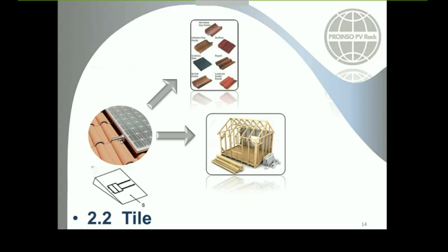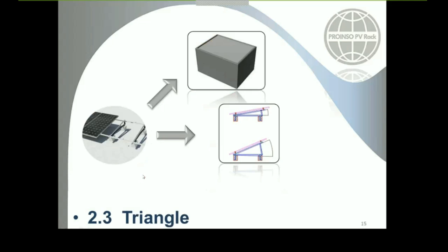We already have a length for the fixing, and if you have a superimposition of more length than this, that should be revised, okay? And as I previously mentioned, the distance between the rafters, because obviously that is the point where we are going to fix our structures. In this case, the configuration that this kit allows is the portrait one, okay?